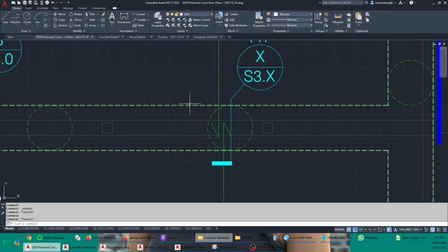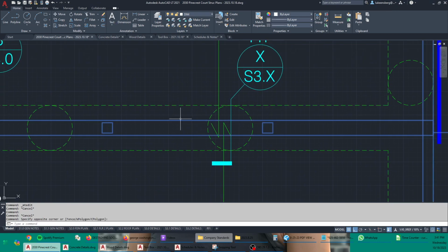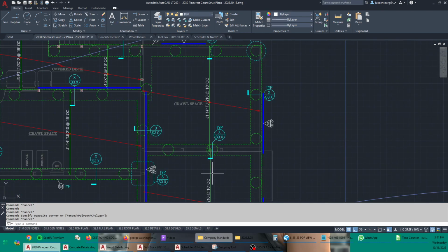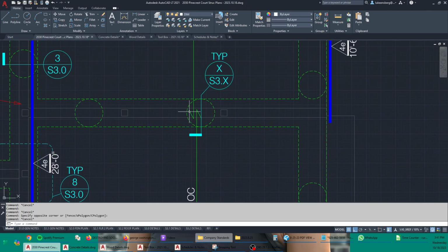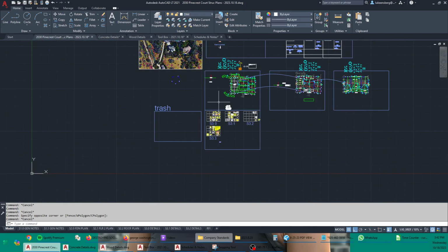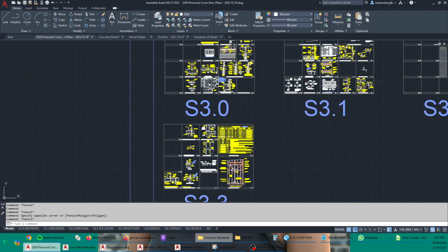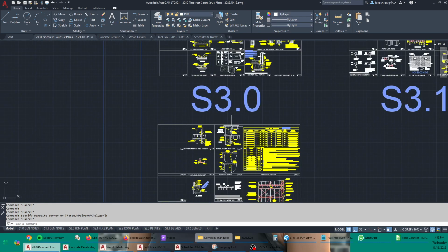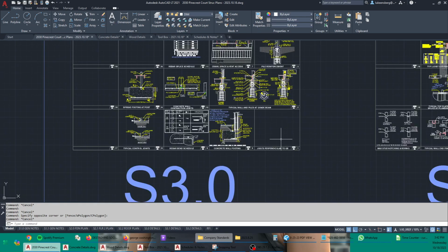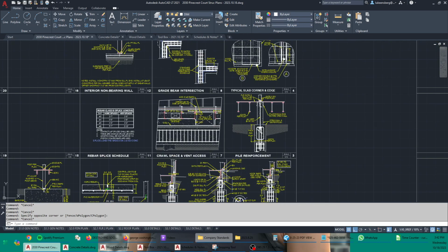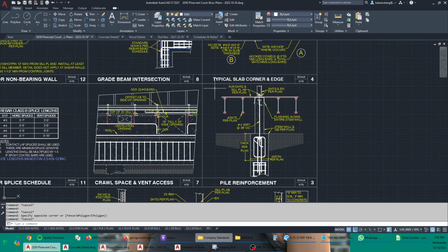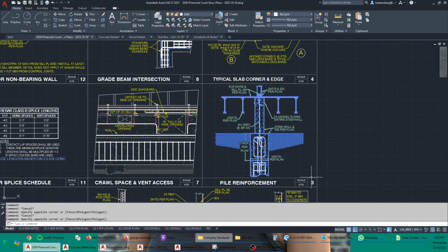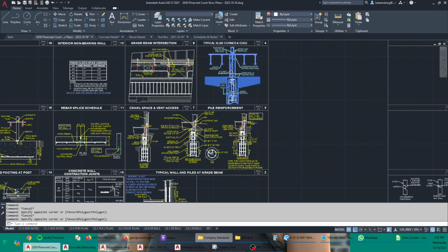It's a 24-inch wide grade beam. There's an 8-inch thick concrete stem wall on top, and then we've got our 14-inch tall I-joists butting up right on top of the stem wall. So I already am kind of seeing a tricky issue here, and I'll tell you about it. So let's get this detail, because what we're doing is going to look a lot like what we did.